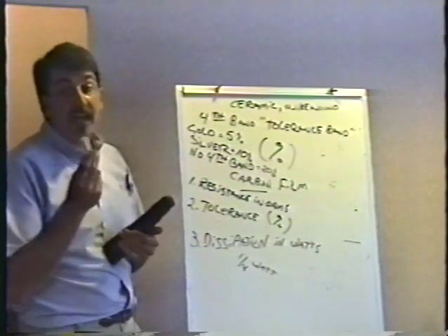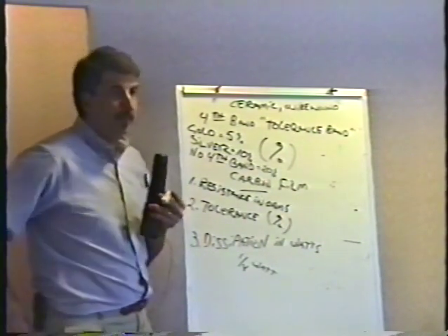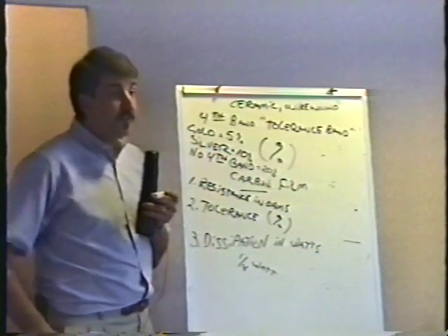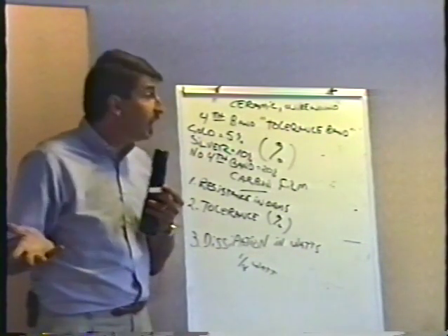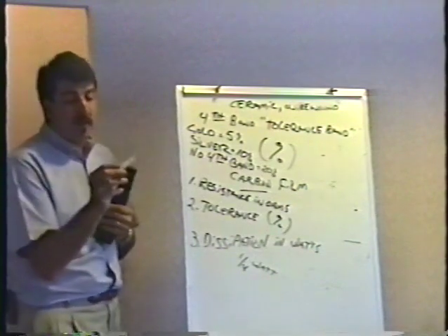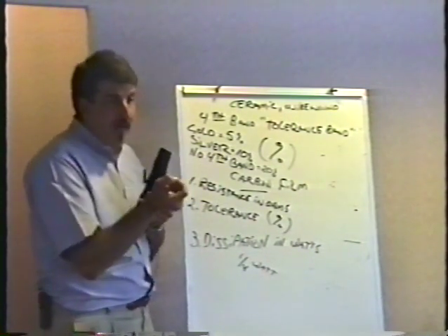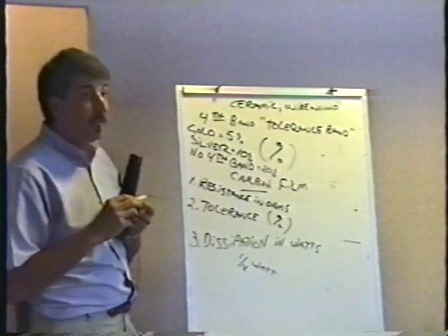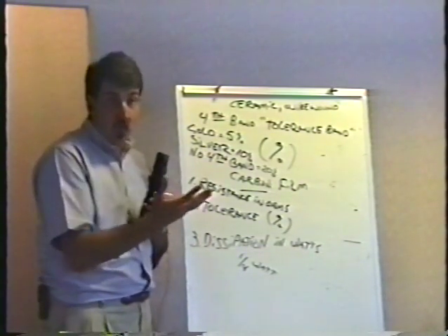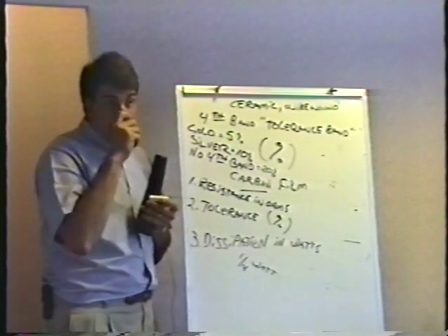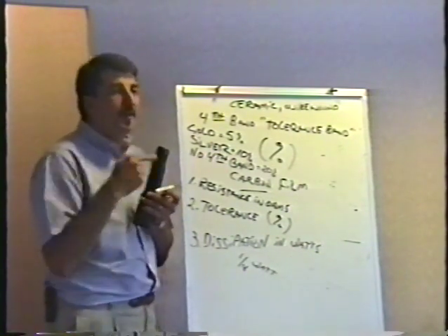They get really hot. In fact, here's a little shortcut you can use to test these things. When I see a big resistor like this, I'll just touch it. If it's hot, it's good, period. Why? Well, because when resistors fail, what do they do? They open circuit. If the resistor's open, no current is going to go through it. It's not going to get hot, right? Actually, that's the way resistors work. The way resistors resist is they turn the current flowing through them into heat. Now, the teeny-weeny resistors won't get hot enough to feel, although they do generate some heat. But I think you're all aware of this thing called conservation of energy that states that energy cannot be destroyed. It can only be changed from one form to another. Remember that? Star Trek 16 where Spock gets caught? Well, never mind. Anyway, the current going through it gets changed into heat.